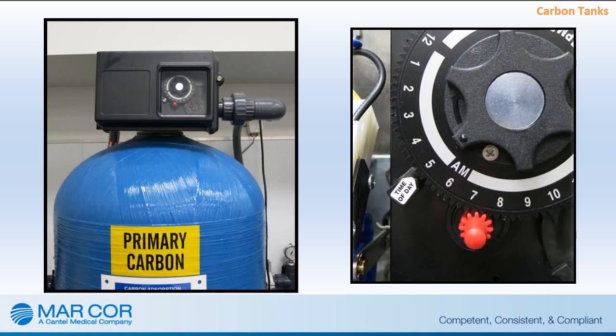2. Operate the carbon tanks with the RO running for a minimum of 15 minutes to flush the carbon tanks and provide fresh water for testing. 3. Test the carbon tank output water to verify absence of chlorine/chloramines and record the results on the log sheet. Using the sample port directly after the first carbon tank, test and record the total chlorine levels at the beginning of each patient shift. Results must be less than or equal to 0.1 ppm total chlorine. Notify appropriate personnel if total chlorine level is greater than 0.1 ppm.